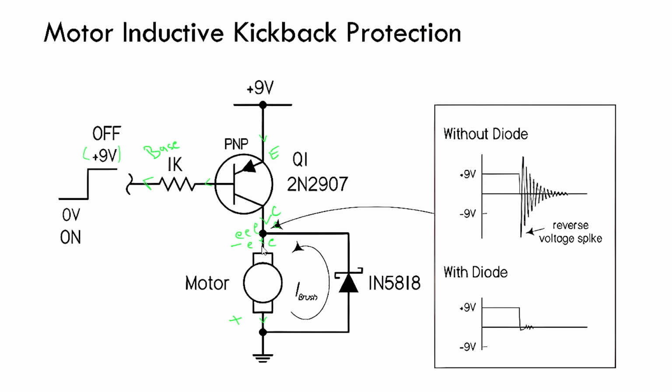So we added one Schottky diode here. The Schottky diode creates an alternate path for these electrons to flow in this circuit. When someone suddenly turns off the transistor by providing 0 volt at the base, these electrons are created suddenly and flow in the whole circuit, and then they disappear. The current flows in the opposite direction, and it disappears with time.